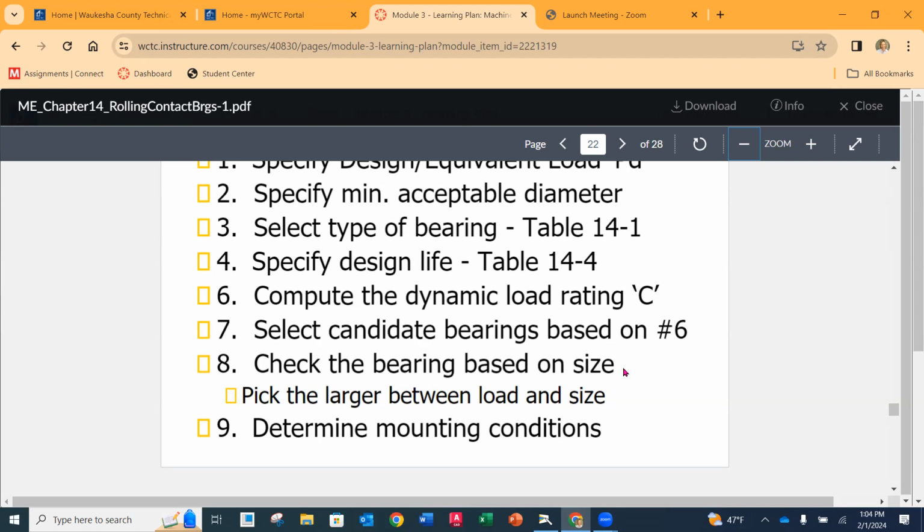Number 2, you could have too much press, so that when you compress those bearings, they're not going to get the life that you're expecting out of them because you're inducing extra deformation that they're not anticipating. So you have to use manufacturer's data for the mounting conditions, and you will do that for me for your problems because I want to make sure that you're getting that. And those tolerances are what you add into your designs.